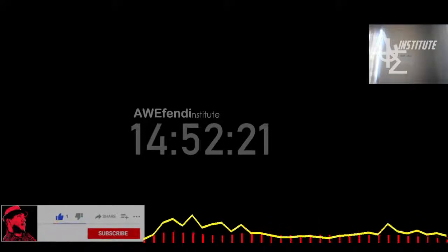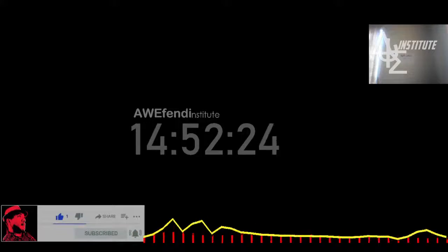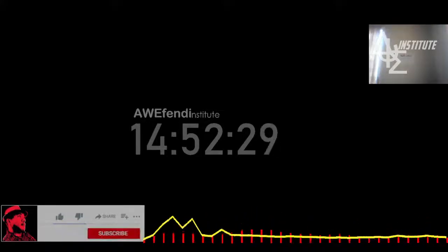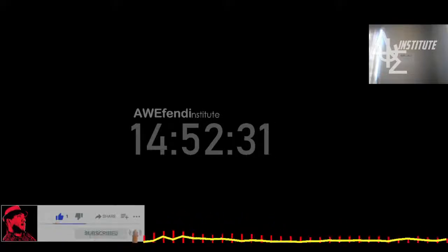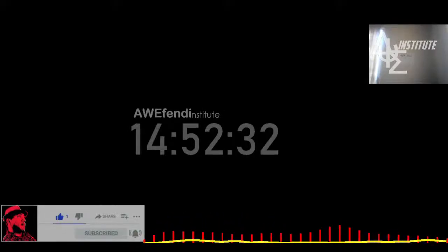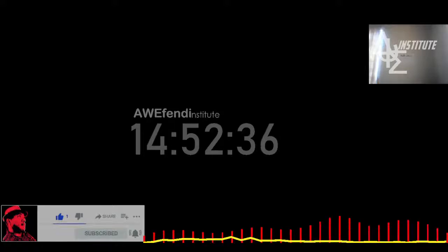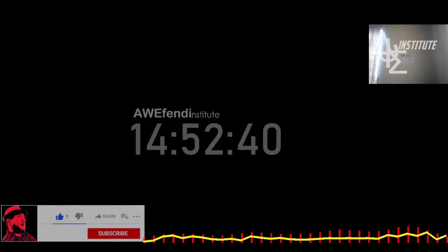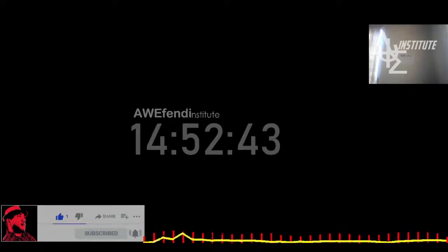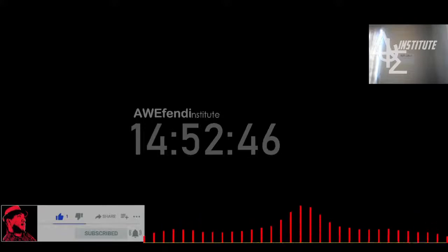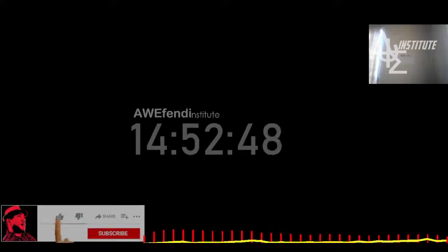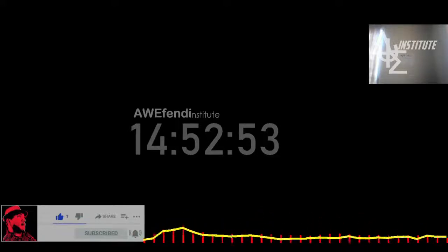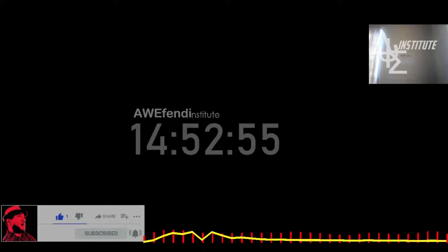However, what's going to happen when we start using our computer and do computing intensive things, and more heat is going to be generated? As I mentioned before, we can go from a few watts to almost 100. So let's see what happens when I change this boundary condition from 10 watts of heat generated to 100. I'm just going to change the number. The simulation is updated live, and we can see we go from 45 degrees to 256. And this is too much, and it's not acceptable because probably our components will start melting and not functioning properly anymore.